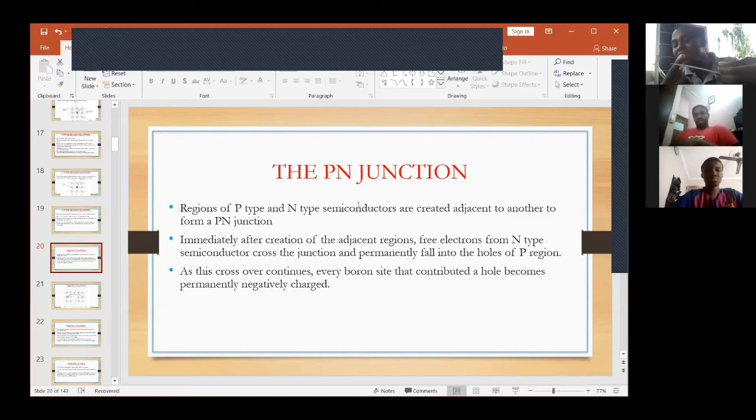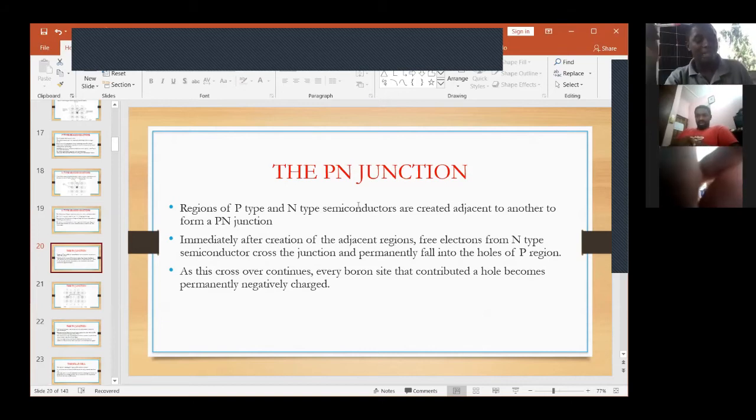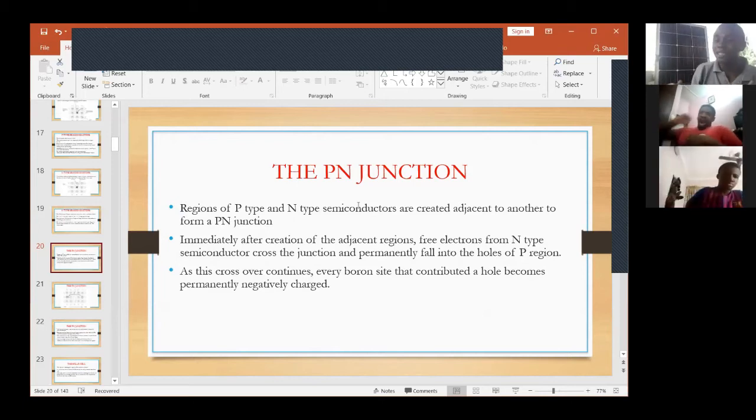So the only direction electrons can flow is from the positive one underneath to the negative one on the top. So I explain again: you have the positive one under, and the negative one on top. As you push electrons from here to this place, they go through the cycle and return back to this place. And that is the basis for a solar cell. Now, if you combine several cells together, you form a solar panel.